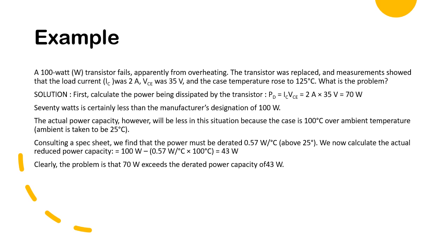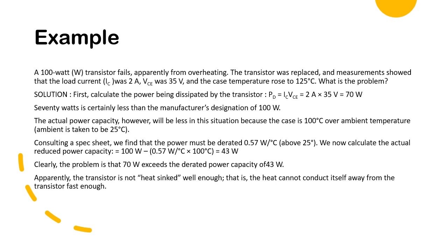Clearly, the problem is that the 70 watts exceeds the derated power capacity of 43 watts. Apparently, the transistor is not heat-sinked well enough. That is, the heat cannot conduct itself away from the transistor fast enough.